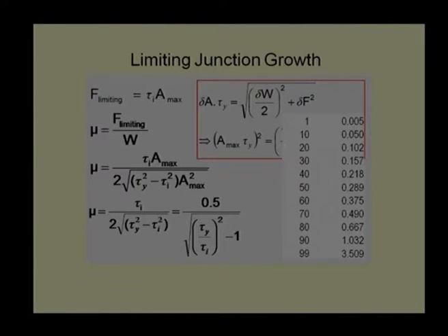The experimental result shows that when two soft materials are used, their interface shear strength will be very high, almost equal to the weaker material's shear strength, and the coefficient of friction can be very high, maybe 3 to 4, or the 3.5 we are getting from here, right.